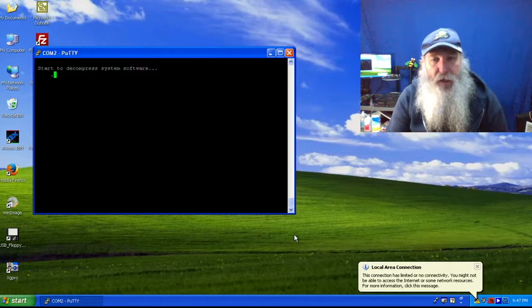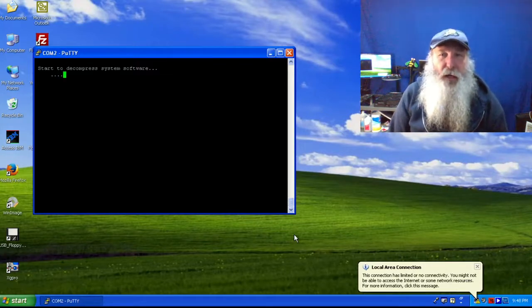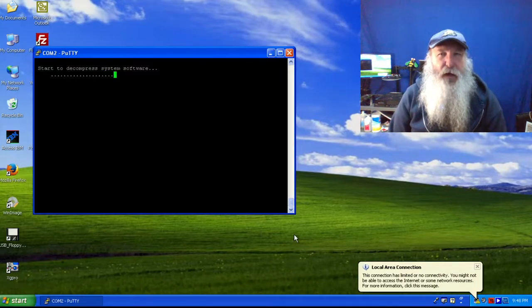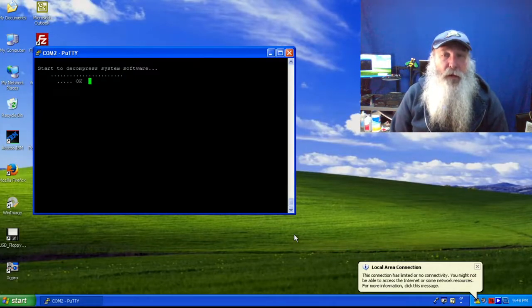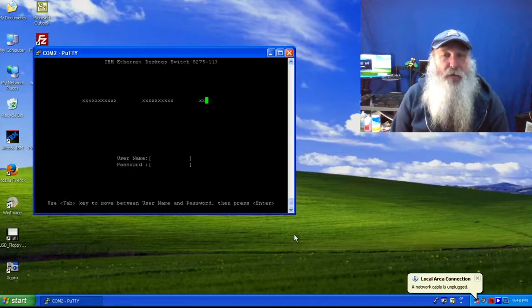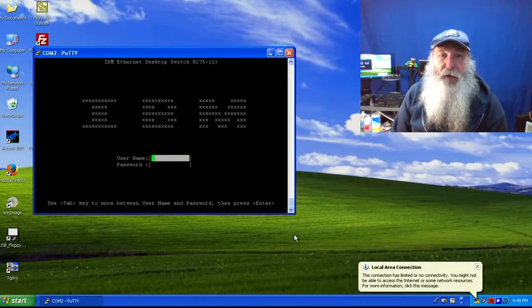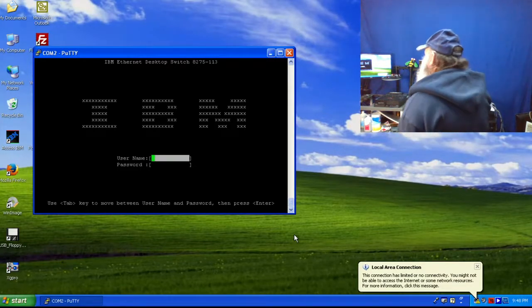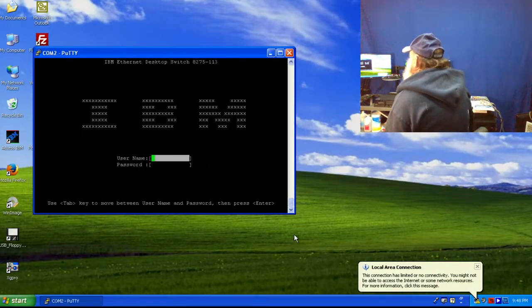And again, it's going through and doing the warning. We don't have any IP address values set on this station for now, and we're just going to set some IP addresses. And I think, as I say, that the AS400 is 192.168.69.4, I think, is my memory. And I'm going to go ahead and put the .3 address on this station. The reason I'm doing that with the network cable in is I want to try to get connected to the web interface on this system. So let's take a look at that.